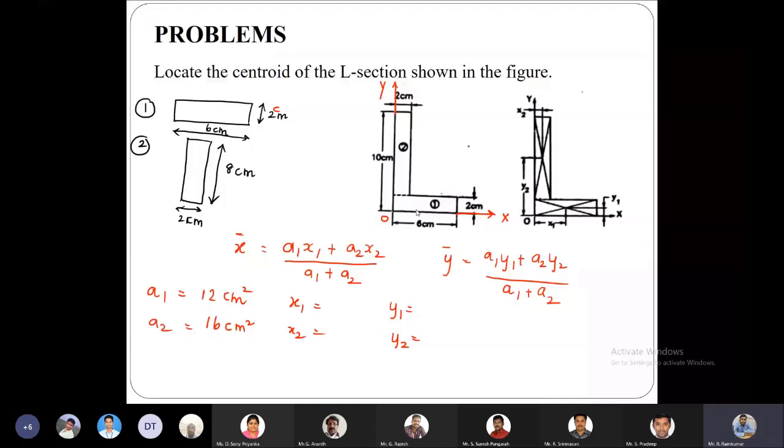Similarly, for the case of the same material, we have the y bar value as the product of V1 y1 plus V2 y2, etc., up to Vn yn, everything divided by the sum of all the volumes. So this is the case for composite solids, whether they have the same material or are made up of different materials. Here the value of rho is the same, and similarly, assume a case when the value of rho is different. For that we will be using the formula given at the bottom.